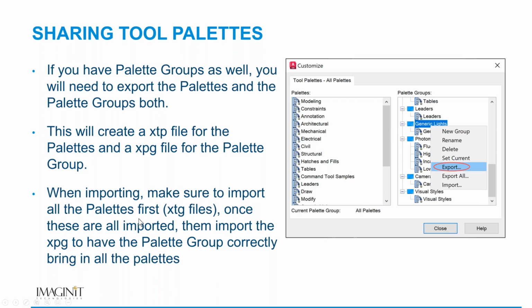Is there a way to open a PDF from a tool palette? Like if I wanted to link our CAD standards PDF to the tool palette for an easy reference? Yes, there is a way to do that. There is a command. There's a specific shell where you want to do more or less a file open PDF where you're opening shell. That's a little more complicated, but Brett, it can be done. It'll basically open up a PDF and open up your default PDF reader.